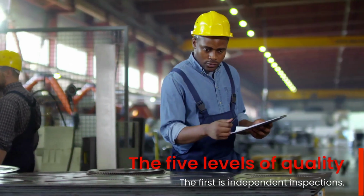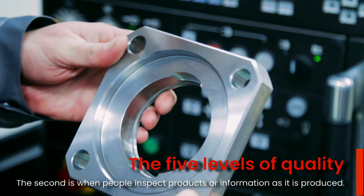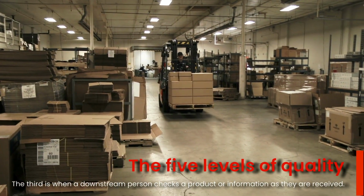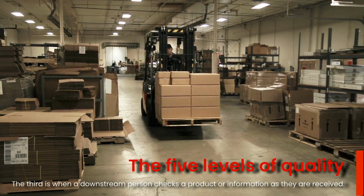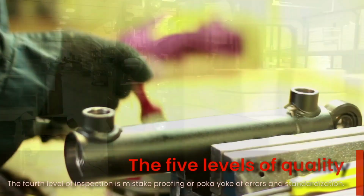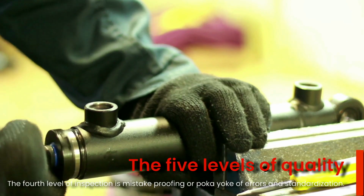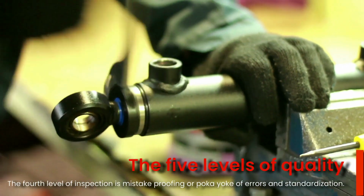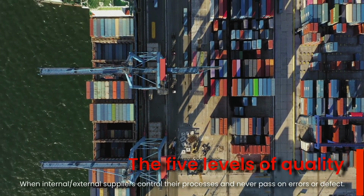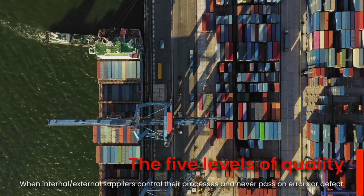The first is independent inspections. The second is when people inspect products or information as it is produced. The third is when a downstream person checks a product or information as they are received. The fourth level of inspection is mistake proofing or poka-yoke of errors and standardization. The last level of quality is when both internal and external suppliers control their processes and never pass on errors or defects.